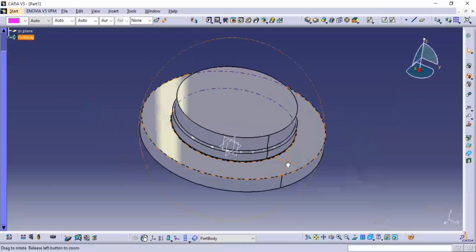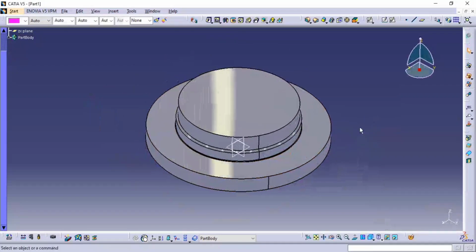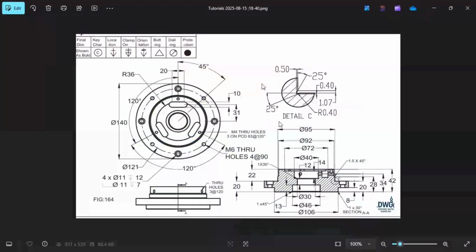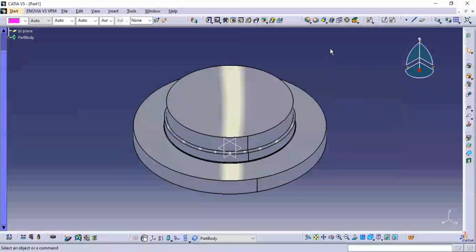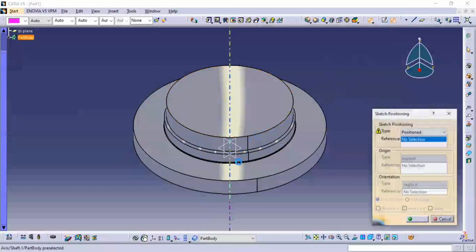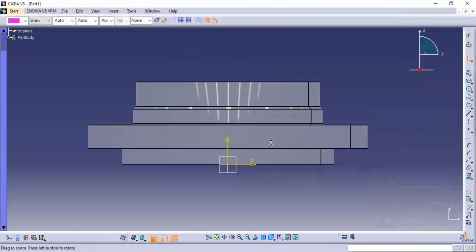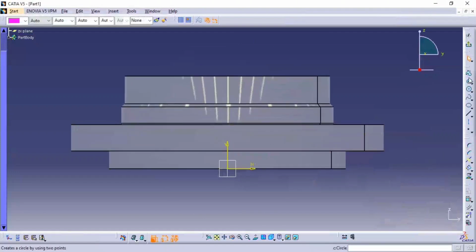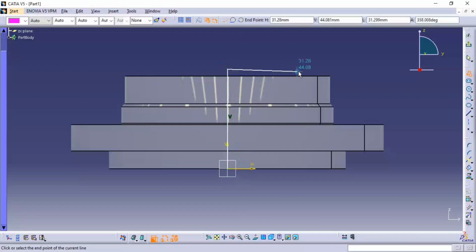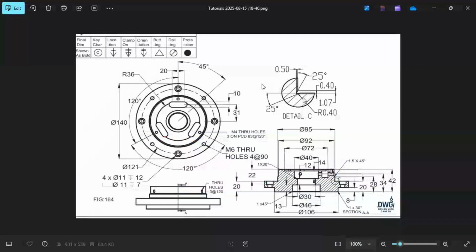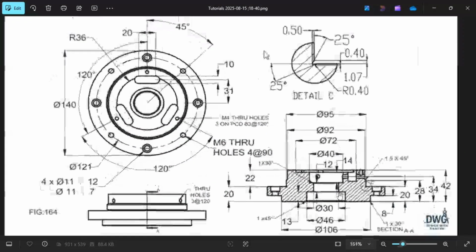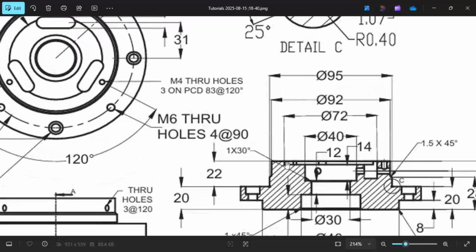See, the next thing is we have added the material only and we need to cut the inner portion. For that, use the position sketch, front plane again, click OK. Zoom it. Now let's make a profile here. The straight line is mandatory. And after like this, zoom it. So see here.